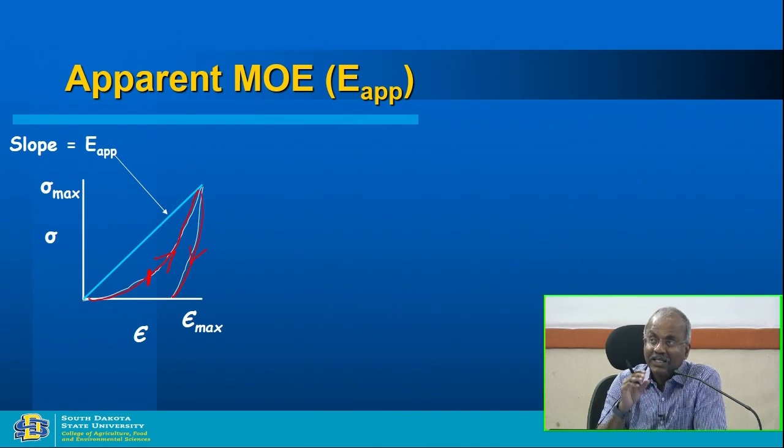Here we are talking about only the solid material, I mean, only the elastic component. Sorry, it's not even the elastic component. The elastic component is only up to this point, but this is also plastic here. So whatever energy you cannot recover, that's lost energy. Here we are not talking about rupture at all. We are still within the yield point or something like that, but still because it has a viscous nature, that is not recovered.